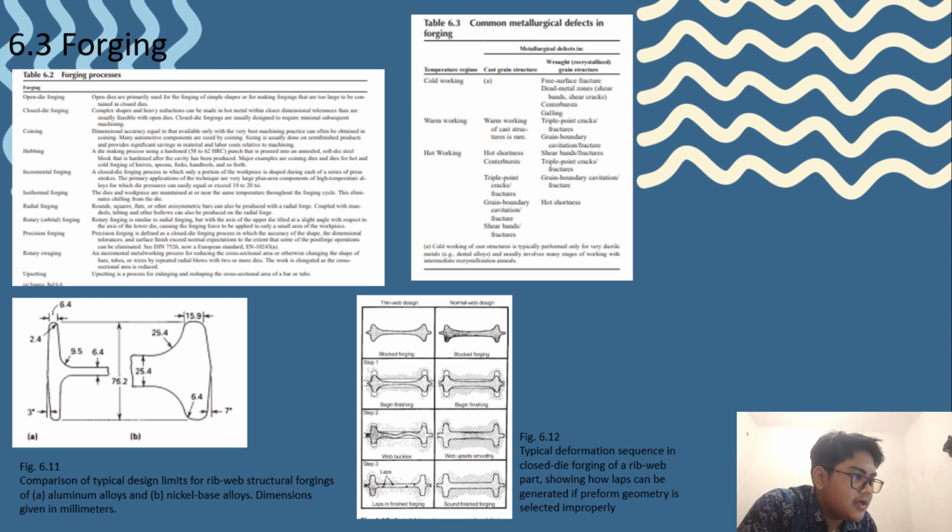Then we get to roll forging, also known as hot fork rolling, a process for simultaneously reducing the cross-sectional area and changing the shape of heated bars, billets, or plates by passing them between two driven rolls that rotate in opposite directions and have one or more matching impressions in each roll. The principles involved in reducing the cross-sectional area of the work metal in roll forging are essentially similar to those employed in rolling mills to reduce billets to bar.